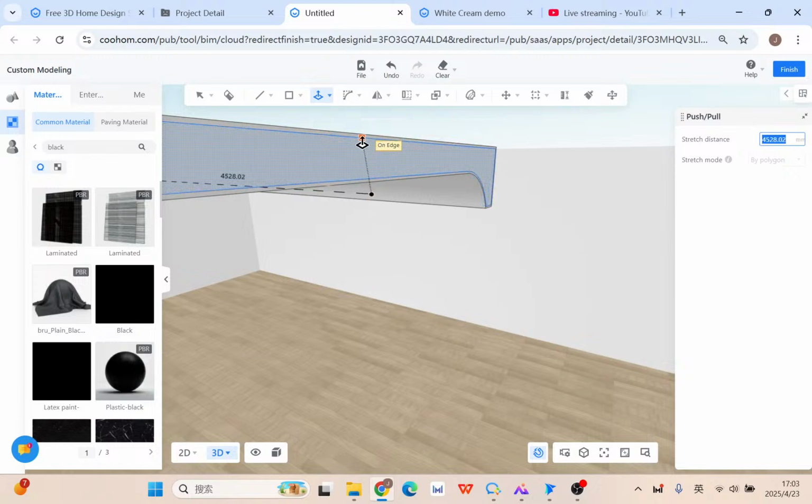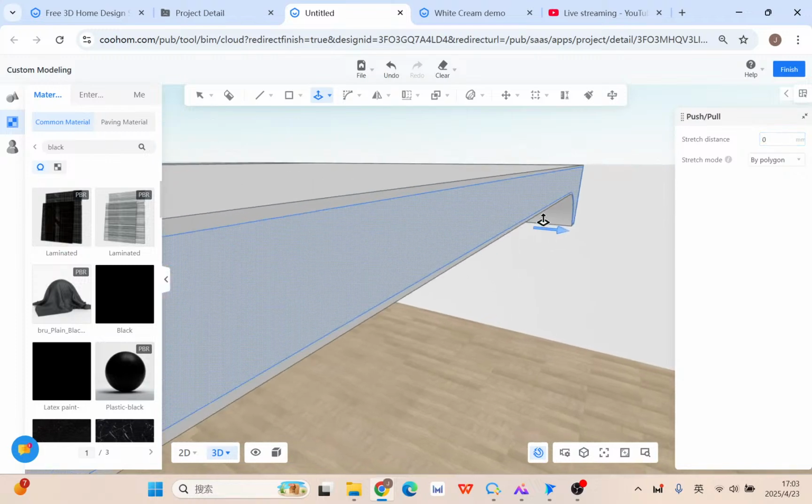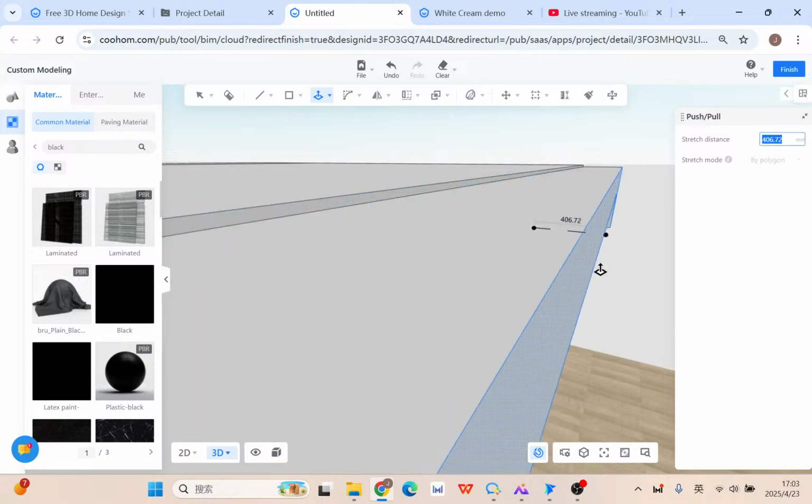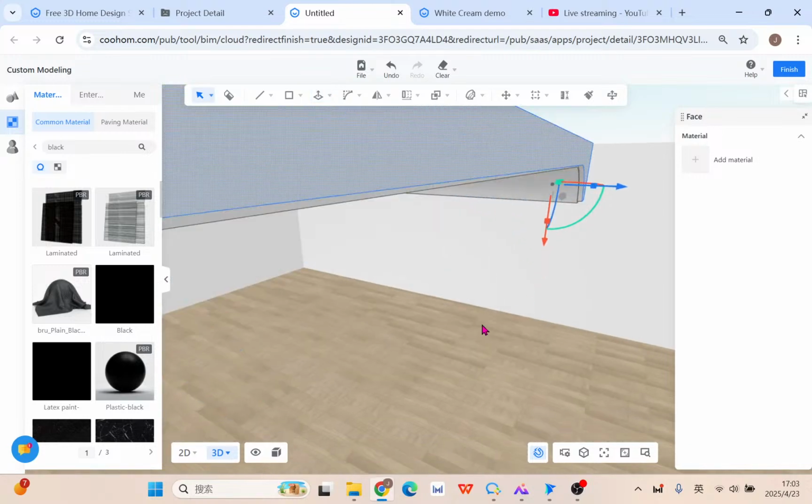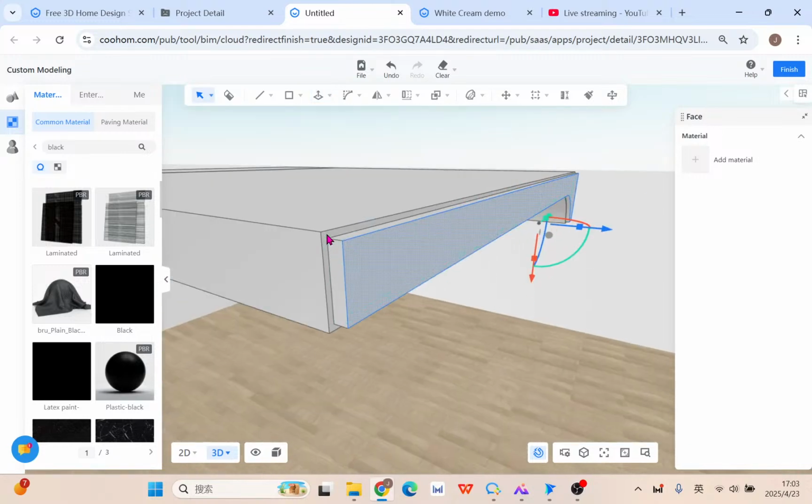And even this time, when you do some pushing or pulling and you already have the existing texture, you can first directly click the boundary on the same surface. You don't have to remember any distance or depth, and then continually click for some more. This time 50 again, and then the same.